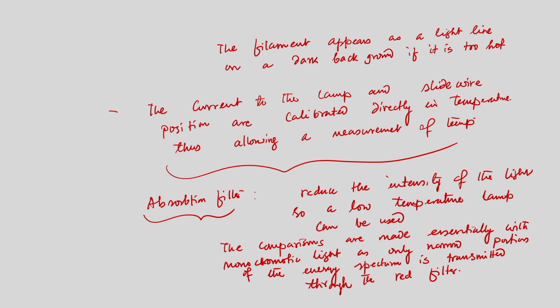So, this is important. The advantage is that using this method we do not require any direct contact with the object or point where the temperature is being measured, and that is why it is purely non-invasive. But a limitation of this method is that the temperature of a point or object which you would like to measure should produce visible light. If the object is unable to produce light, we cannot use this method to measure the temperature. So, this is one of the limitations.